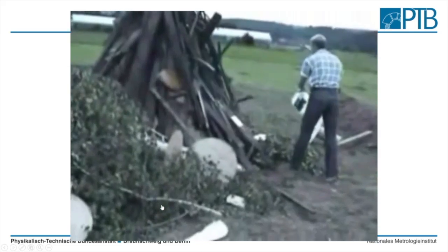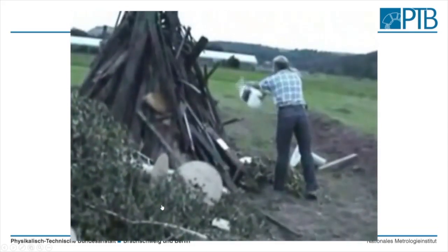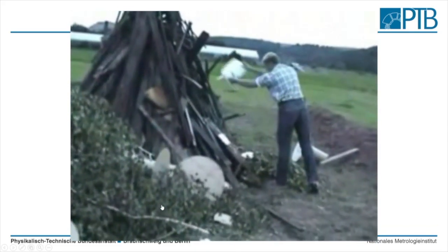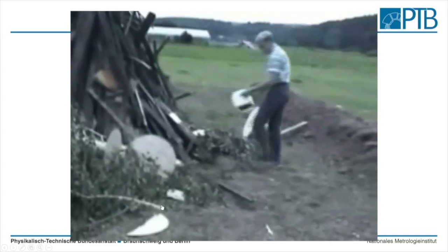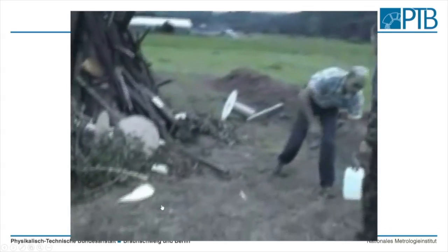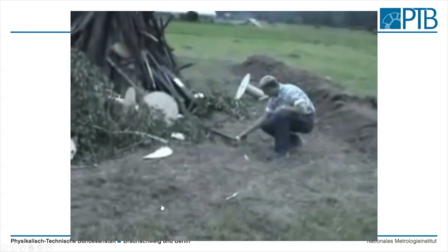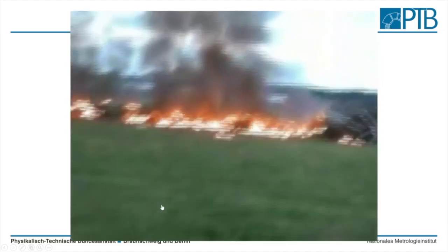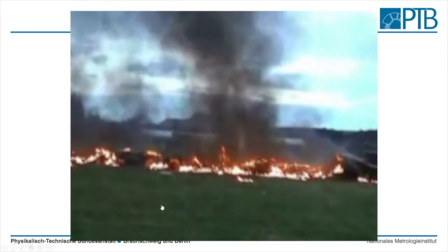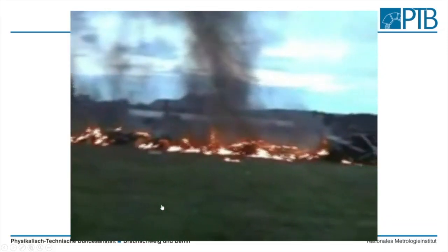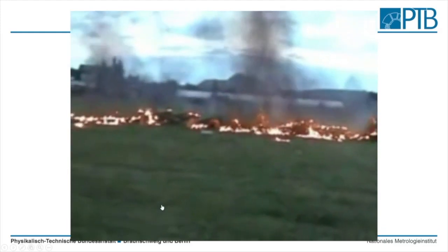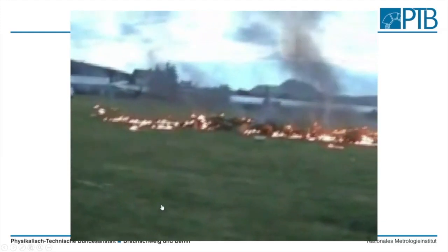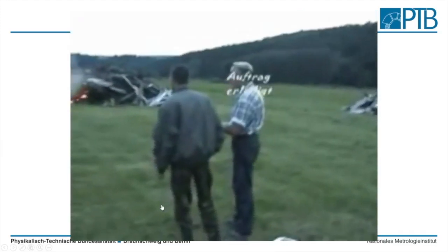Okay, here we have some rest of gasoline. It will help, of course, for burning. So everything is empty, and now with some safety distance he will ignite the system. But he has not realized that, of course, gasoline has a high vapor pressure, so he was in an atmosphere of gasoline and air. And he has not ignited the liquid gasoline.